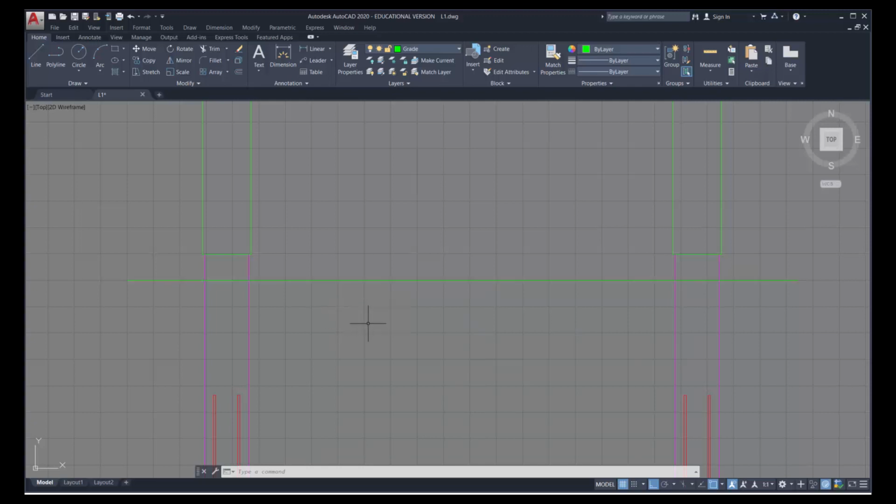Now, this is a P-line property or a P-line object, and therefore I have certain properties I can associate with it. To edit a P-line, we type in P-E-D-I-T or P-edit and press Enter. Now, if you weren't able to do that, press Escape and try it again. It's asking for a polyline. If I click on something that's not a polyline, it'll tell me it's not a polyline. But in this case, the grade is a polyline. And these are the functions we have available to it.